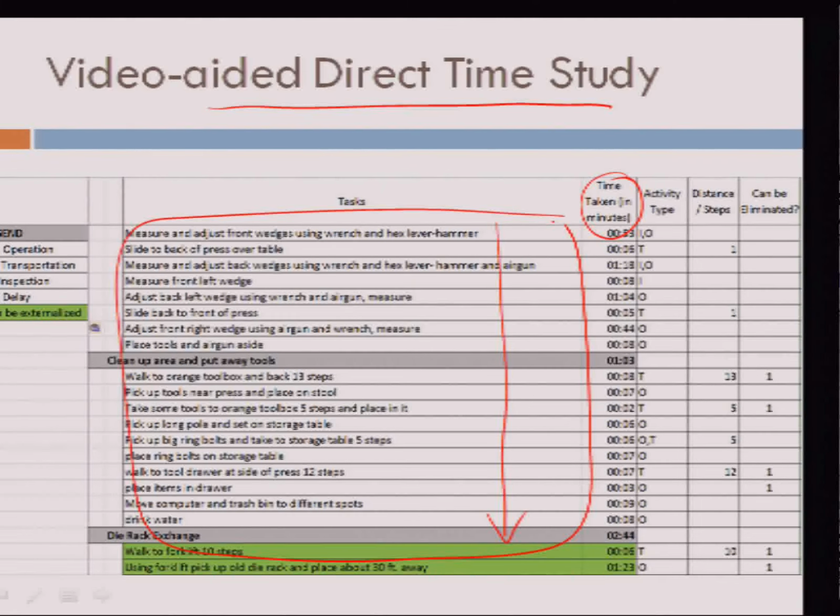Now, this is one of the key process charts that we need, and I'll show you how we use this to create essentially a routing for the operator's movement path. So every step was being done at some location in the workspace. Every time the operator moved between two consecutive locations, that created a travel, and that became a routing. And then once you have a routing of some work being done, you can run it through the production flow analysis software and make some improvements in the workplace layout.